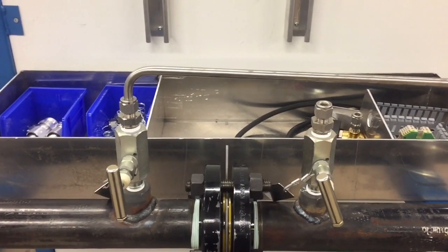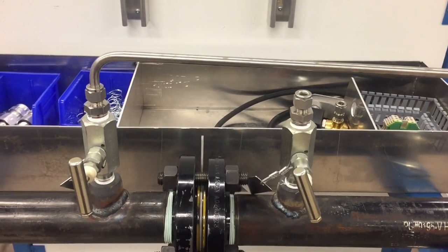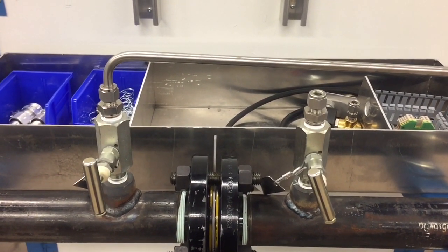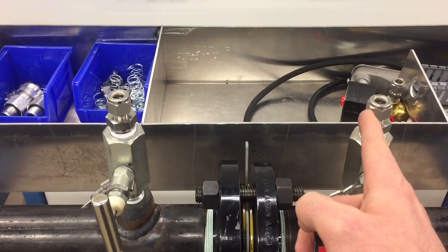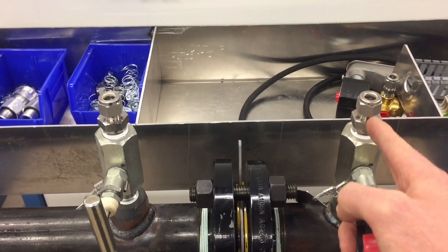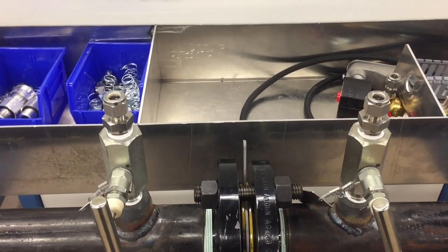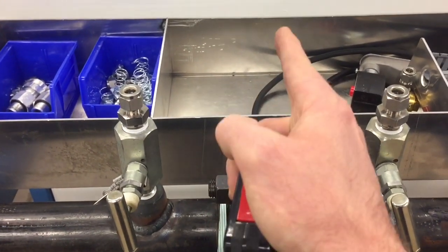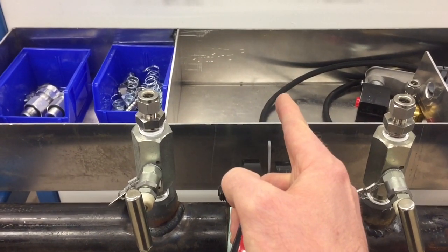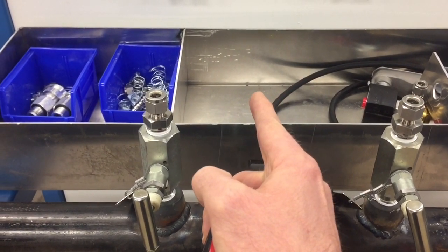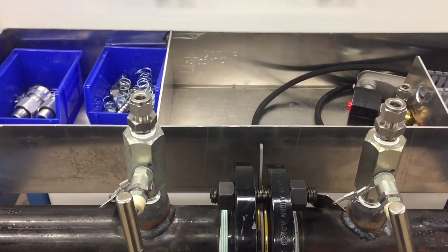So we're going to have to make some measurements. We'll make the measurement between the two needle valves, and we're going to center our 5 valve manifold between those two needle valves. With tubing, we're usually dealing with a center to center measurement, so the center of this fitting to the center of this fitting. We want to measure that center to center measurement between those two fittings and divide by 2, because we want our 5-way manifold to be right in the center here. Then we're going to take a measurement on the manifold to figure out where the fitting is and how much further over we need to bring that, so when we do make our bend, we come right up into the bottom of that fitting.